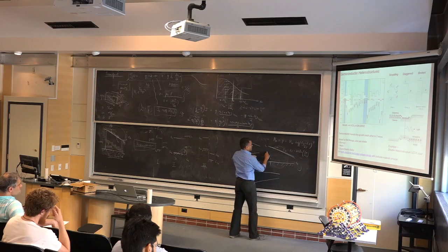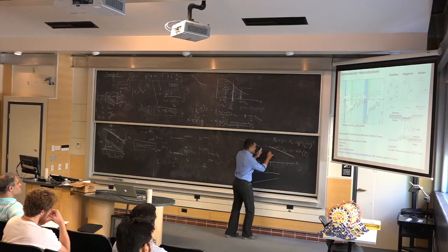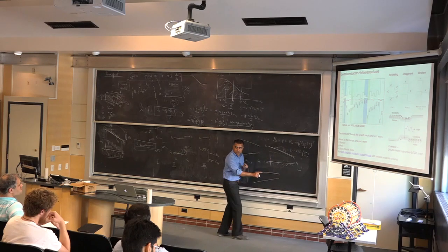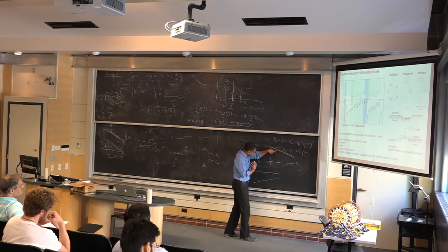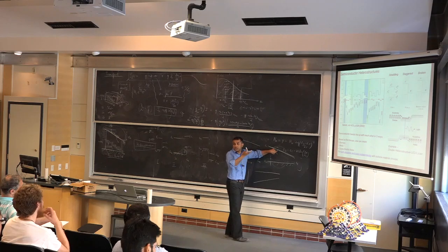Typically, if you don't grade it, you have a flat band here, and you inject a lot of electrons, and they have to kind of diffuse across. Diffusion is relatively slow. You build in this electric field, and the electrons get a huge boost in speed, and the transistor speed goes up by quite a bit, actually.